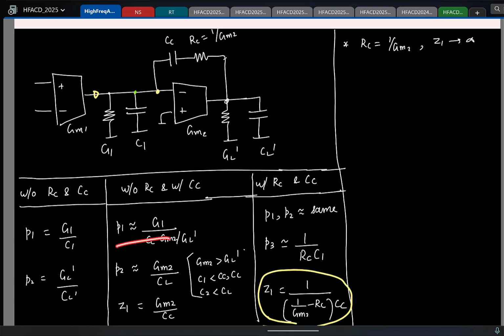Earlier I had 2 poles and one RHP 0. Now I wanted to eliminate the RHP 0. I definitely did that. But in that process, did I introduce something else? I introduced a third pole. So do you think I am doing any better, or I am doing the same as before? Because earlier also these 3 contributed to phase lag. Now also I have these 3 contributing to the same phase lag. So are we doing any better, or we are doing okay?